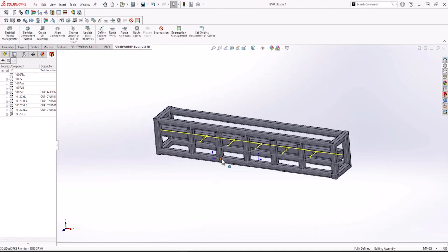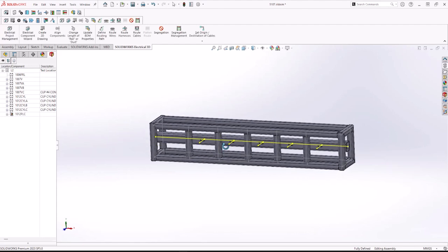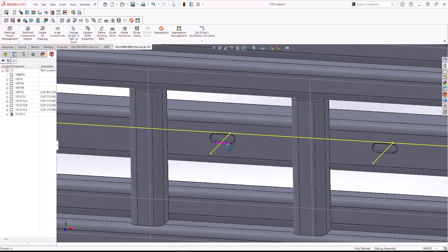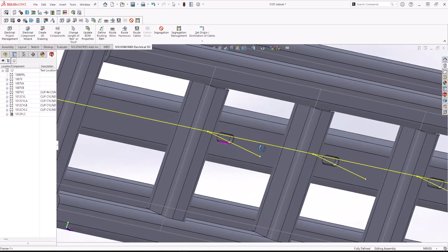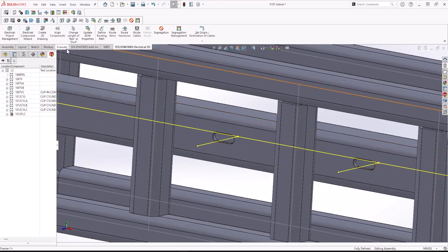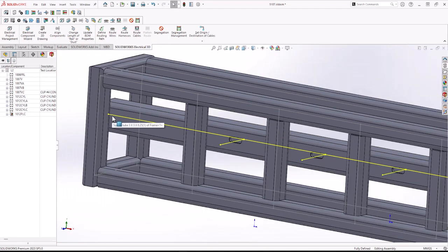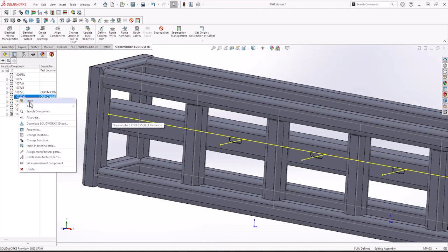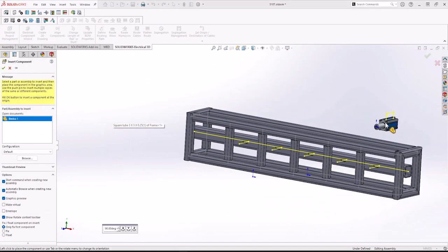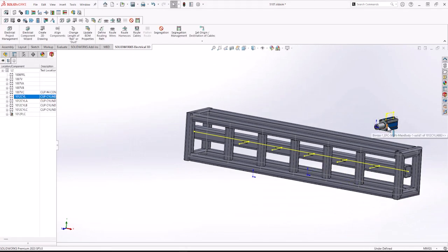And remember, you can add a path inside of any part or assembly, which I have done for this frame. I have added an EW path for the tubing to follow. It can also be for the wires or sensors or anything else. Right click to start inserting, as we saw earlier in the webinar, to be able to just place specific devices.